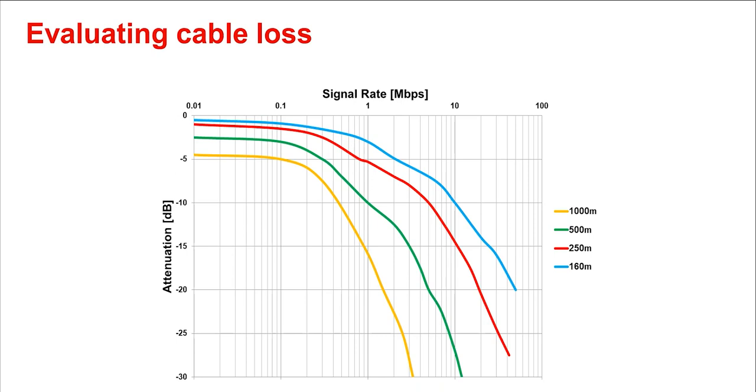Additionally, system designers should choose receivers with positive and negative input thresholds, which are symmetrical and close to zero in order to minimize duty cycle distortion.